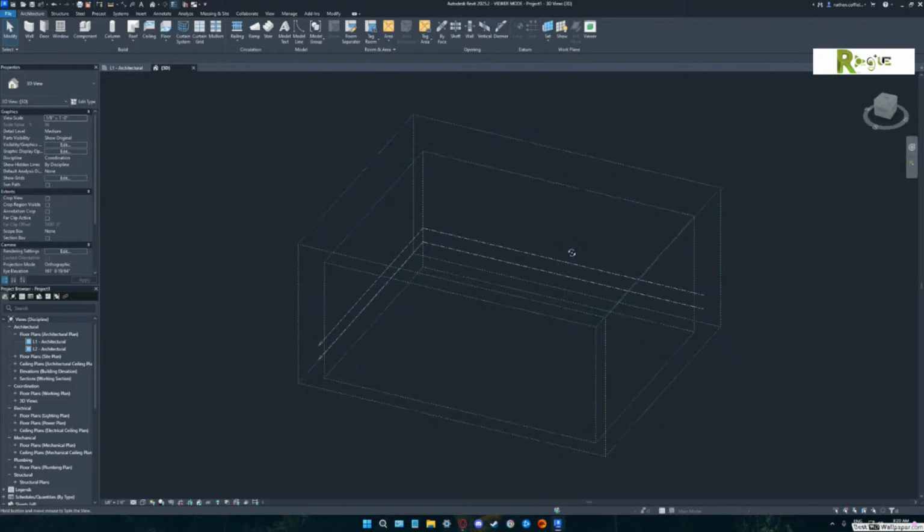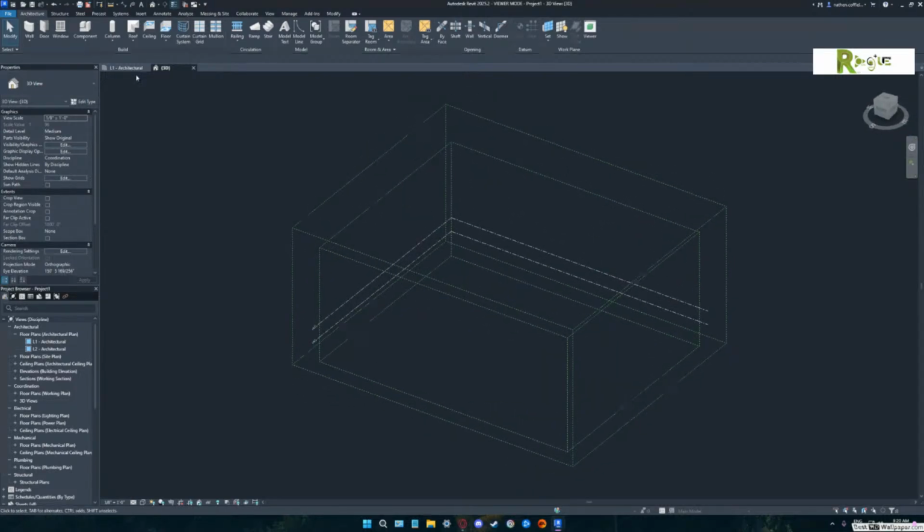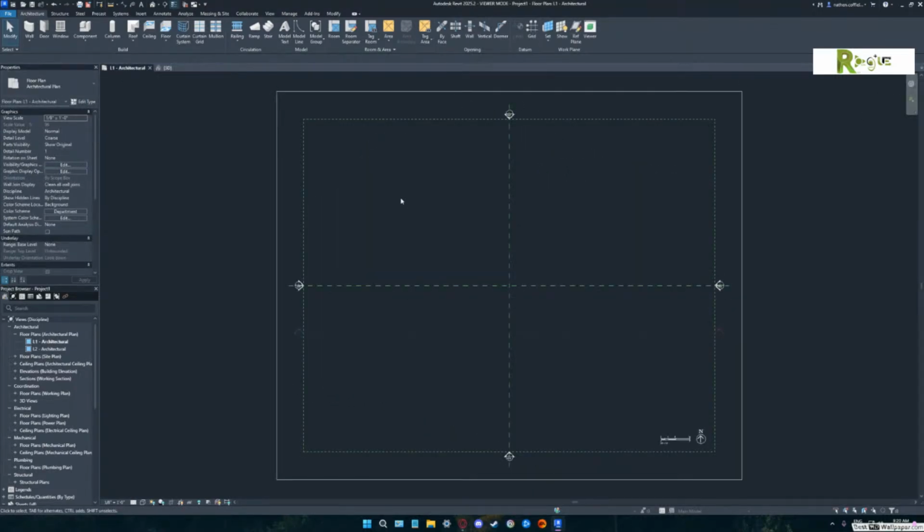Yep, I saw it. Okay, so the first thing that we've got to learn about Revit, and there were some similarities here with the Rhino, but Rhino is much more like AutoCAD. Remember, I used to teach people how to do AutoCAD, but the first 2 boxes that you got to get straight when I tell you where to go is the project browser and the properties. And that's over along the left side of the screen. That top little window, that's your properties. And the one below it is the project browser.